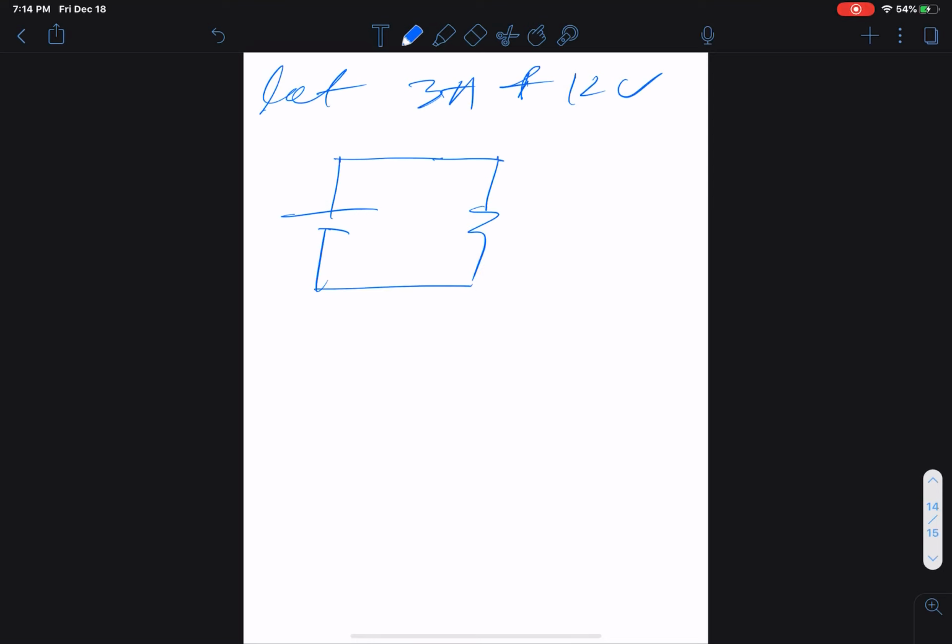What I'm saying is that when your voltage and current supply says limit, you cannot cross the limit. If you set a 3 amp limit and a 12 volt limit for the power supply, and you add a 2 ohm load, you cannot cross any of them.